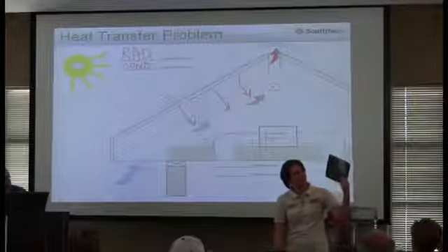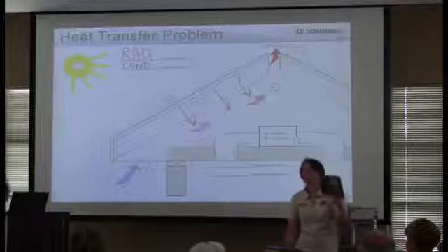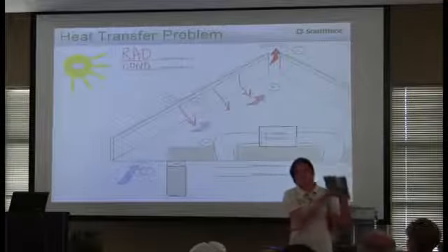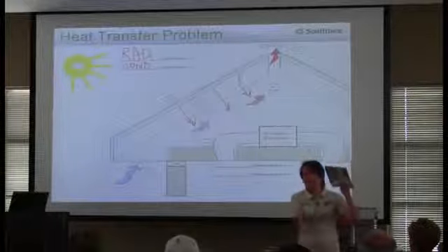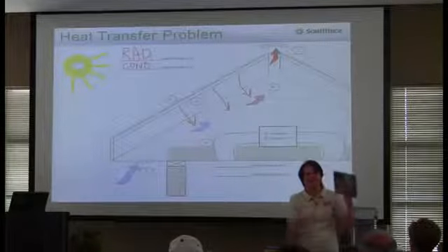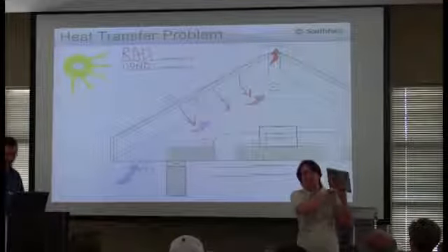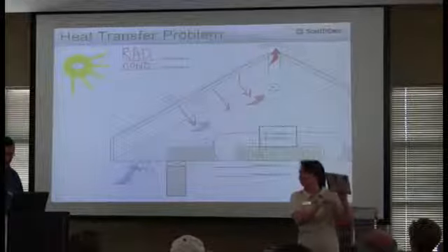So it has to basically not be touching, for example, insulation. You never want to put insulation up against it. You have to have a gap. So you don't want to put this up there and spray foam it. We've seen it. You don't want to do it. It totally negates this. You also don't want to take your ductwork and touch it right here, because you're now conducting 160 degrees pretty easily right there.